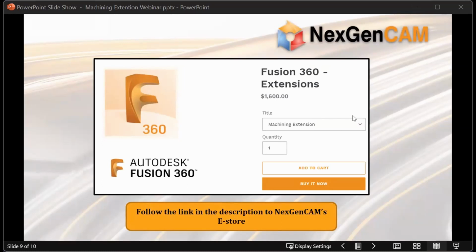Let's see, I have a quick question here. It says, can you use hole recognition for hole-based milling operations? Currently, unfortunately not. You can only use these for just drilling operations. However, if you are looking for something like a hole-based operation, such as a circular bore thread mill, in that case, a patterning option would be really helpful if you're looking to do the same operation, but in multiple different locations. I hope I answered that question. Yes, currently it's restricted just to drilling operations. So that can be anything from drilling, tapping, reaming, any sort of hole operations.